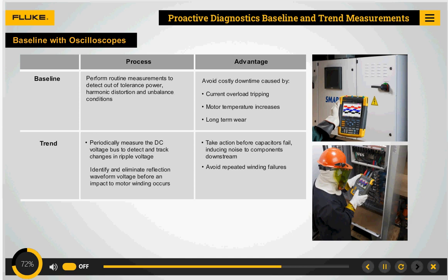This is load dependent. Ripple voltages above 40 volts can be caused by malfunctioning capacitors or a drive rating that is too small for the connected motor and load. The DC bus voltage is approximately 1.414 times the RMS line voltage.